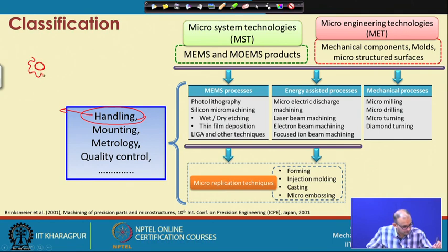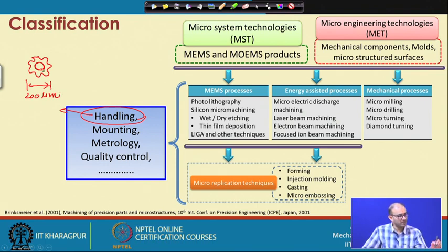Now consider that suppose you have one gear. Now, this gear dimension you consider, it is around 200 micron. Now, you have fabricated it, and you want to transfer this gear to some sub assembly. If you transfer directly, that means by your hand or some other type of gripper, then there is a chance that it may deform or it may break in different locations.